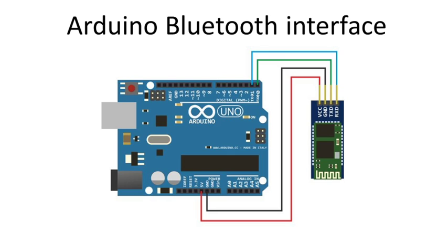Over here I have used only 4 pins, and those 4 pins are connected with the microcontroller. Which 4 pins are we using over here? That is very important. The TX, RX, you can see over here, and then 5 volt and ground. How you connect these is very important. The RX of the Bluetooth module should be connected with TX. You can see in the figure how to connect RX with TX, so that you can integrate it for your applications.